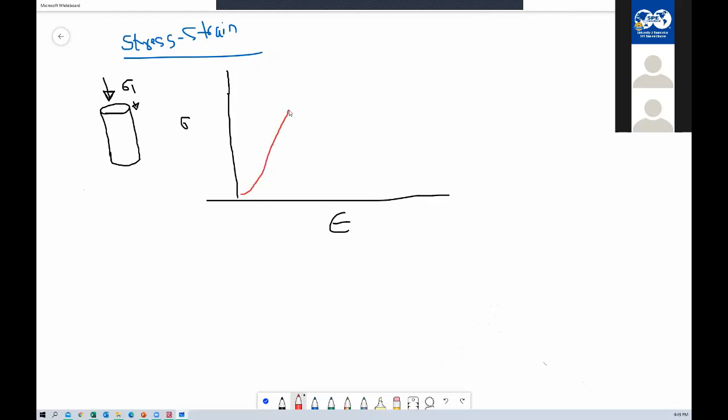Stress is proportional to strain up to a certain point, and then it starts deviating and goes to a top point where the rock is unable to bear any further stress. Then a lot of fractures get created, a failure plane is created, and this rock will fail. The rock will be broken after this point, right? This is the peak load. This is the peak stress the rock can bear.